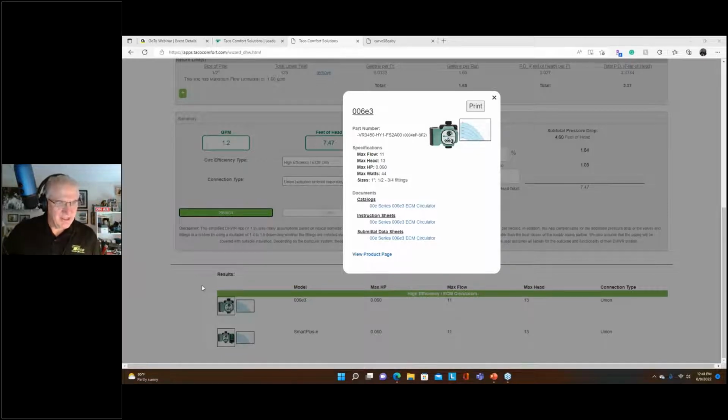It's a good one. In a retrofit, what happens if it's too difficult to get to the last fixture? Well, then you won't have hot water recirculation at that last fixture, I guess, Carmen. If you can't get to that last fixture, and you connect at a fixture further up the line, you simply won't have domestic hot water recirculation at that last fixture.